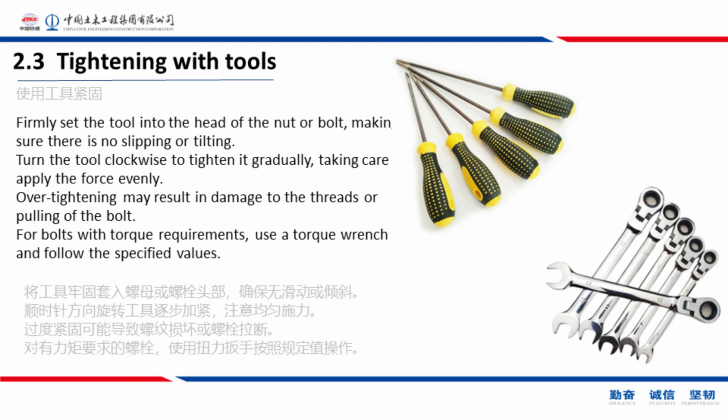Over-tightening may result in damage to the threads or pulling of the bolt. For bolts with torque requirements, use a torque wrench and follow the specified values.